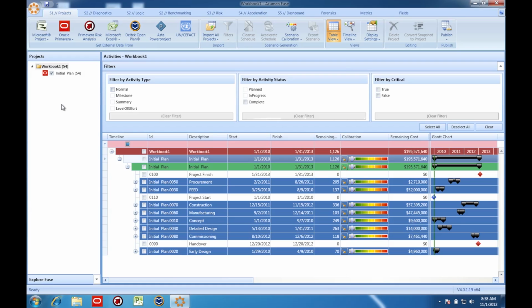Scoring is a key method in Fuse to quickly understand the overall health and quality of a schedule. To be most effective with the scoring options, it's important to become familiar with the options and to carefully plan the scoring method and the metrics utilized for scoring. Acumen Fuse allows flexibility to determine whether or not the score is displayed, how the score is calculated, and the extent to which each metric affects the overall score.